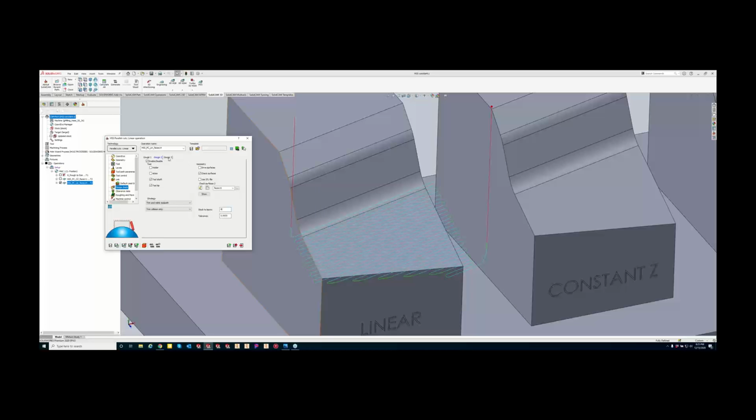And we can keep adding gouges in here as well. So gouge 3, maybe we want to do a check surface against a bolt, and we want to clear that bolt by 10 thou. We can put that in there as well. So that is our gouge clearance data here. We can set up clearance data for our holder, basically our safety. So if it gets within 100 thou of the holder, the arbor, tool shaft, and the angularity limit there, as well as our roughing and more.